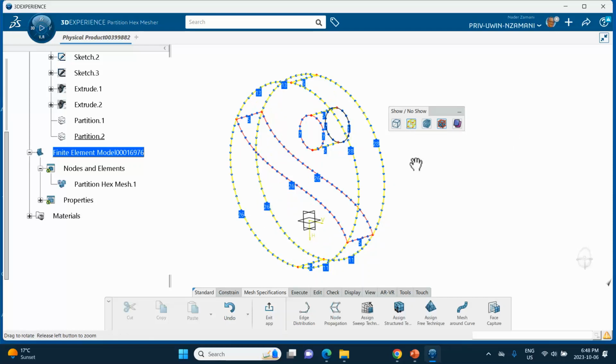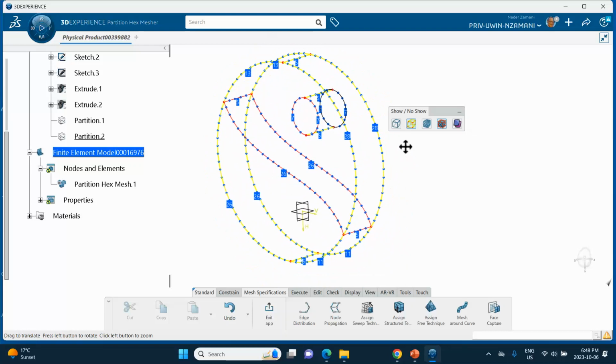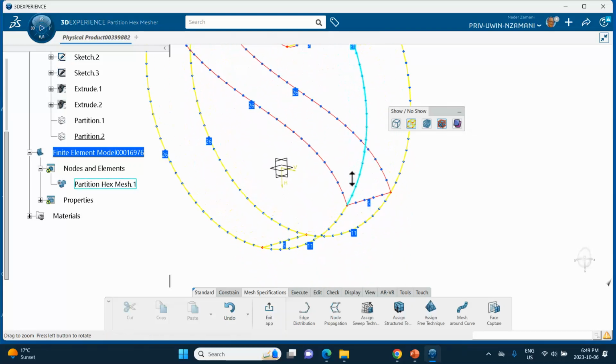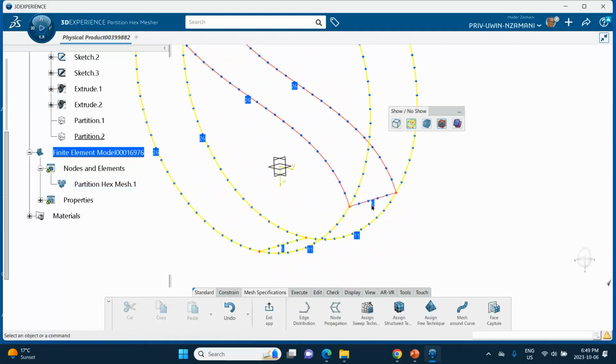Hide that. Okay. It showed you the seeding, and notice that in the length direction, for example, here it says, what does that say? 6. So 1, 2, 3, 4, 5, 6 in the length direction. You want to change this thing to 1, 2, 3, 4, 5. You want 2 in this length direction. Okay, 2 nodes or 1 node. If you want, for example, let me see now.